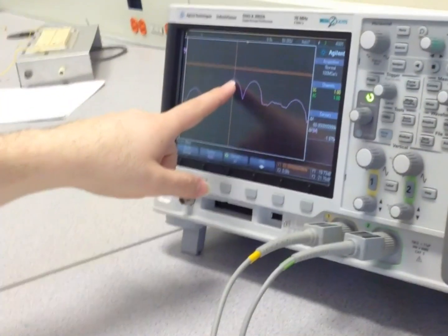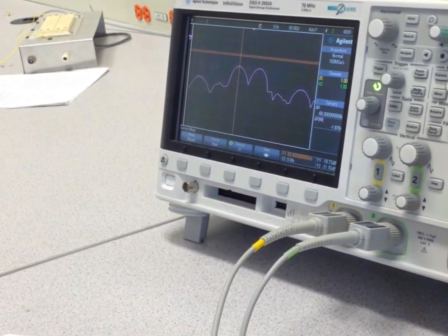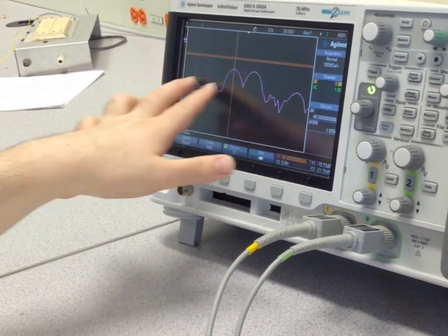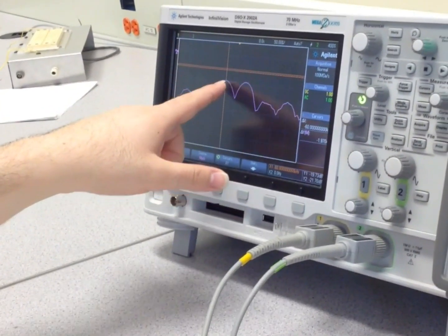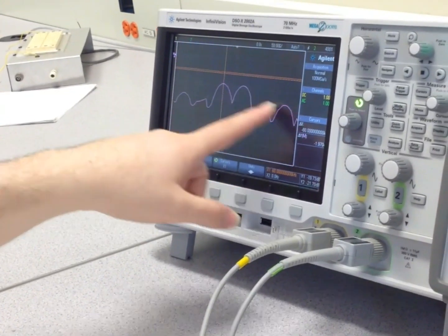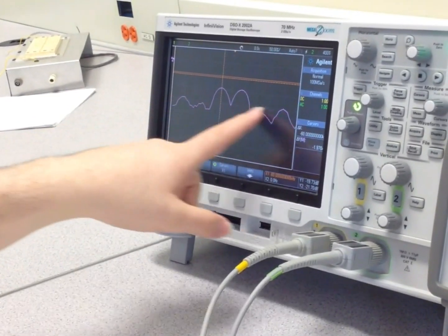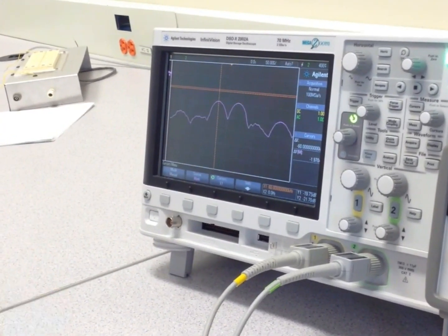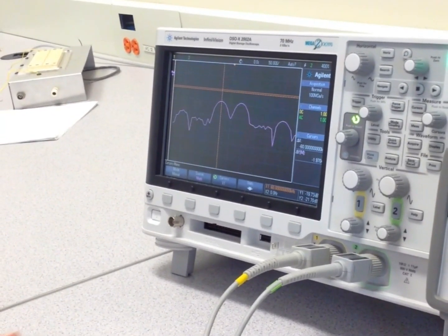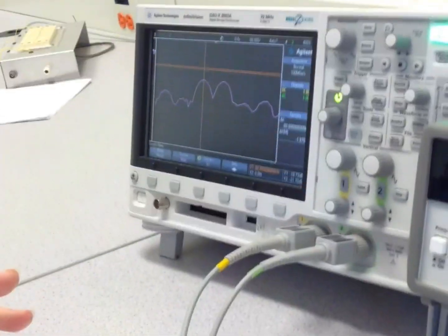Okay, so this is my message, and it appears at 60 kilohertz and 68 kilohertz, but still there is some noise because my input signal was actually a square wave. I filtered it using a non-ideal filter, which didn't get rid of all components.